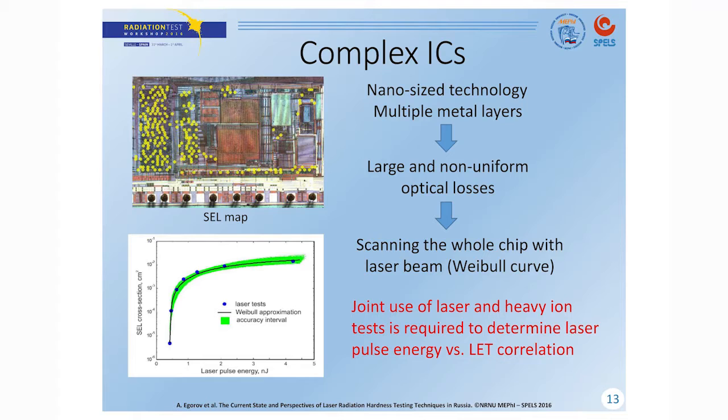Sometimes the optical losses in such ICs are so big that we can't measure the saturation part of the curve. So we have to use shorter wavelengths to increase laser radiation efficiency and to produce single event effects with lower pulse energy.